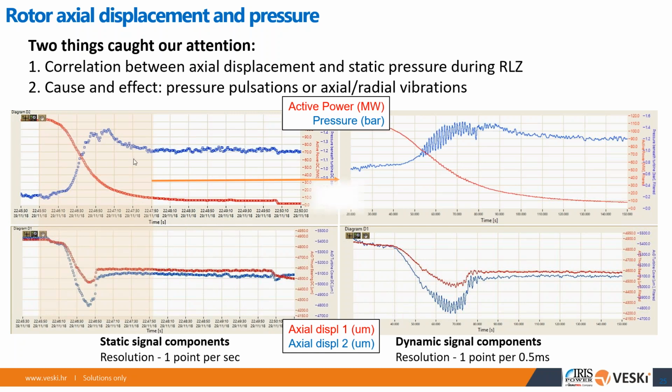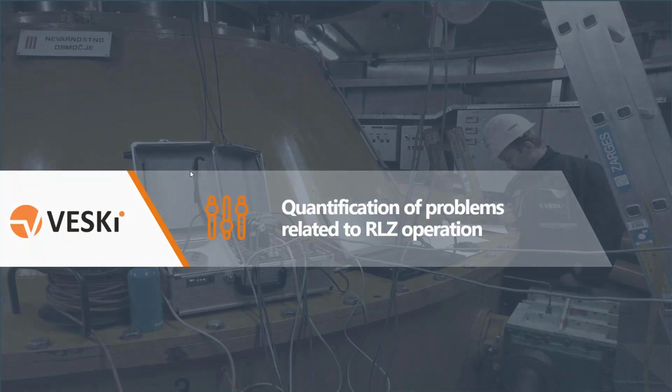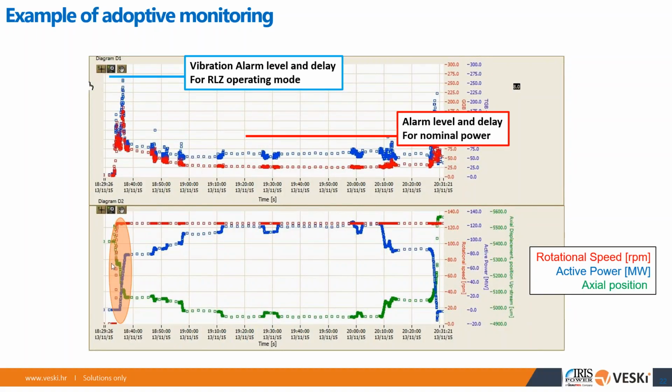Okay, this is the power decrease, but I think I maybe have the power increase like this. This is typical, extracted from monitoring, a typical 2-3 hours duration of the operation. This is the start. It happens quickly, and then you just quickly go to a load which is outside of your operating restriction, from 0 to, let's say, 70 megawatts, and then you put it on full power, which is 140. So you just pass through this and hope that vibrations, when you pass quickly, do not have time to really develop. You just basically get out, and then it takes a couple of minutes.